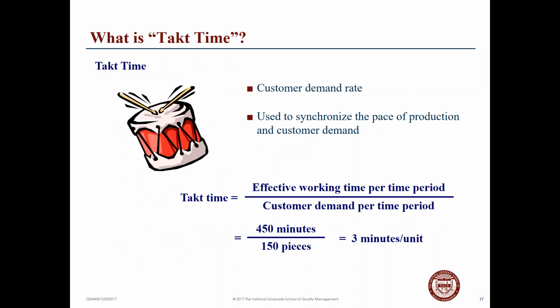So takt time, again, is one of those things people often struggle with. It's how we determine the customer's demand rate, and it's used to systemize a pace of production to meet the customer's demand. And so here we have a formula that shows you how you would calculate takt.